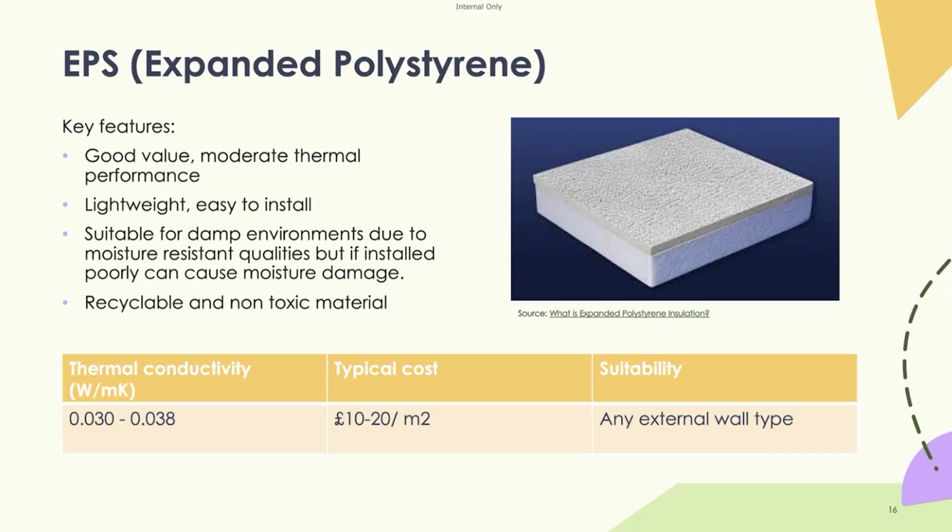But it might be the case that if you're trying to achieve a certain U value, or you're trying to achieve a certain EPC rating, you'll need a thicker insulation product here to achieve the same U value.